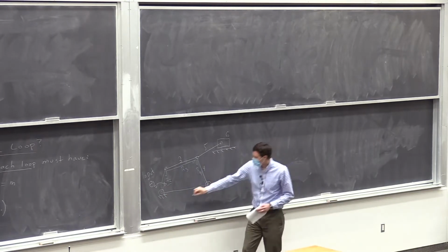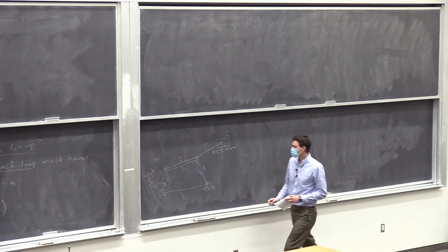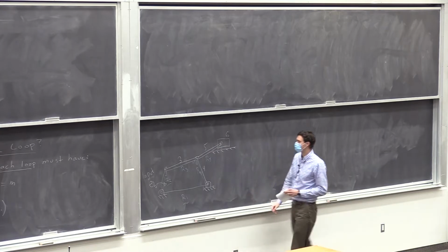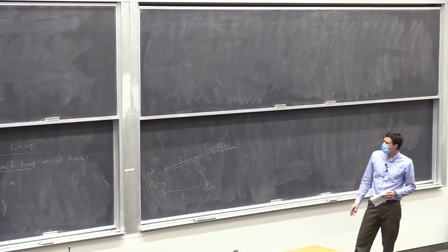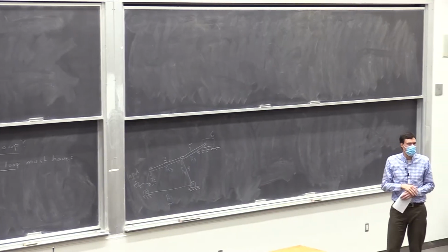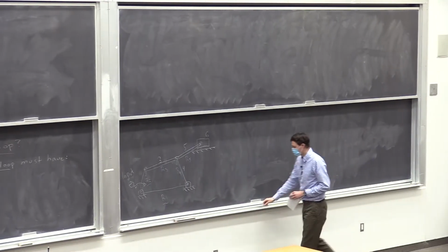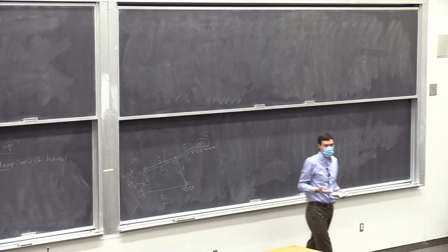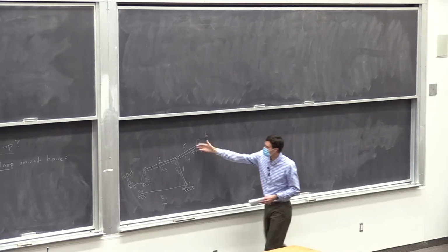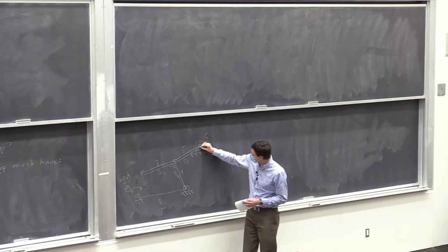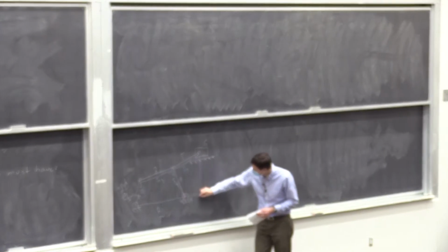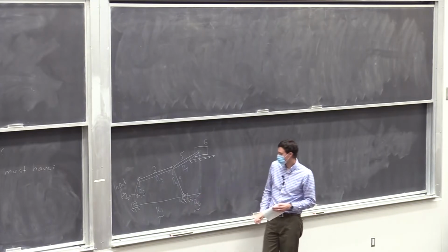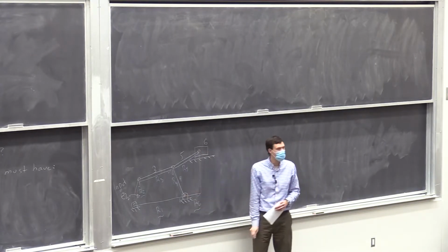We could make a loop here if we wanted. To finalize that, R5 is along link 5. And then link 6, we'd like to track the position of that somehow. Maybe the goal is to calculate the position of link 6 here, left and right. So you could design a vector that captures the horizontal position of link 6. So let's actually do that. I'll call that R6 here. That's the horizontal position of link 6 from that reference point there.